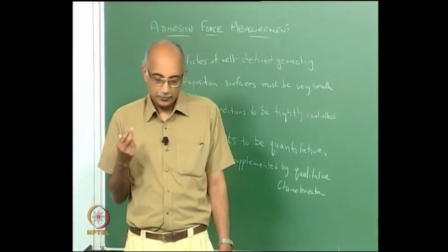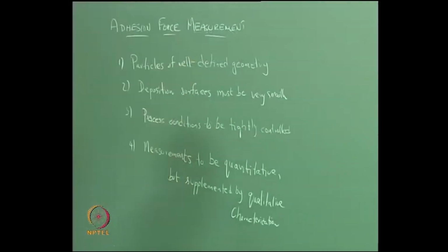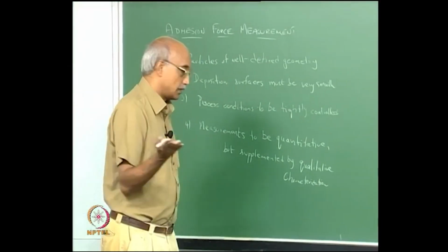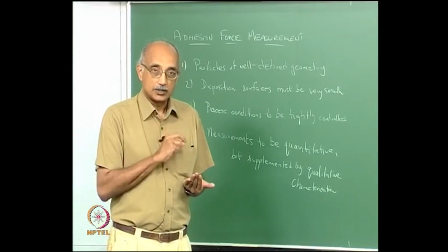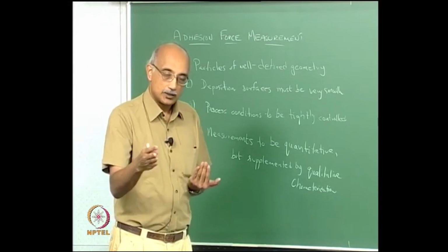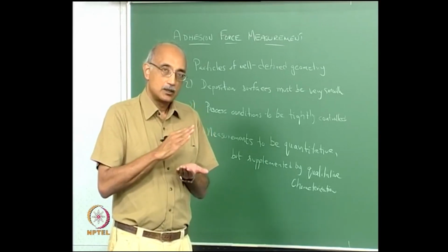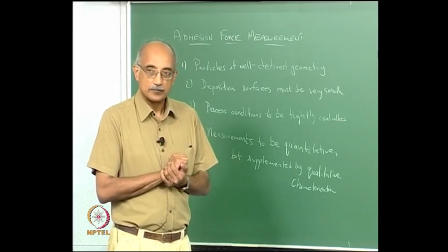As you can imagine, the simplest way to study particle adhesion forces would be to deposit a known number of particles of a known size distribution on a surface, count the number of particles on the surface, apply a certain force, see how many particles are removed, keep increasing the force until all particles are removed from the surface.